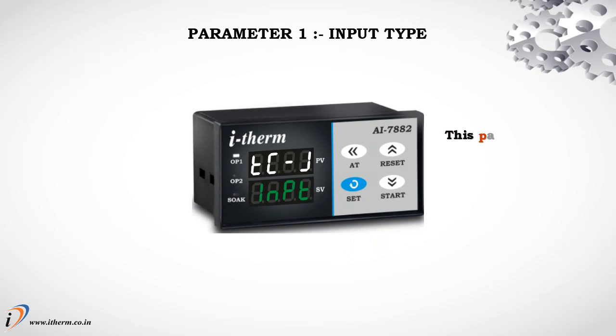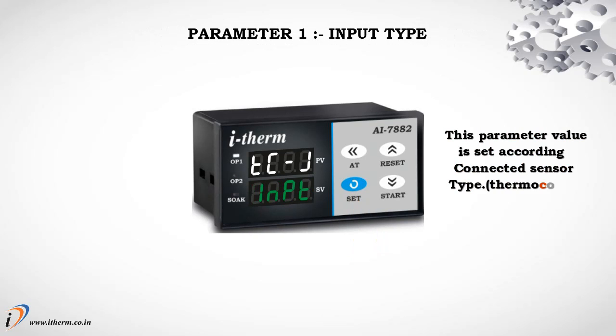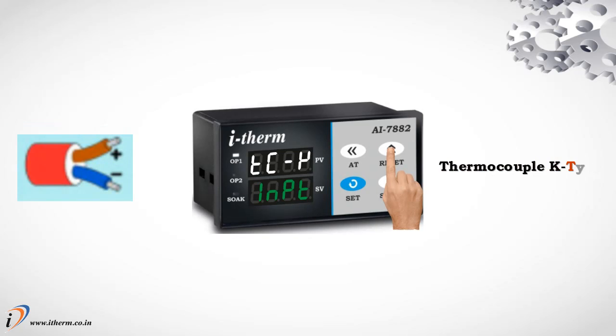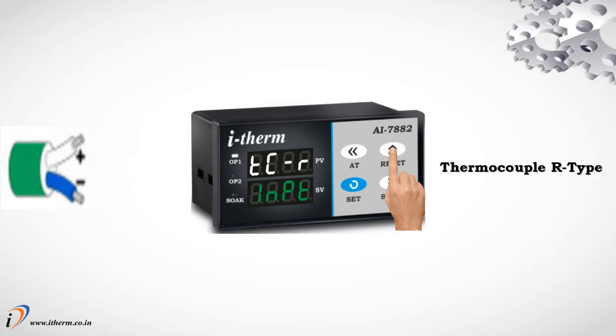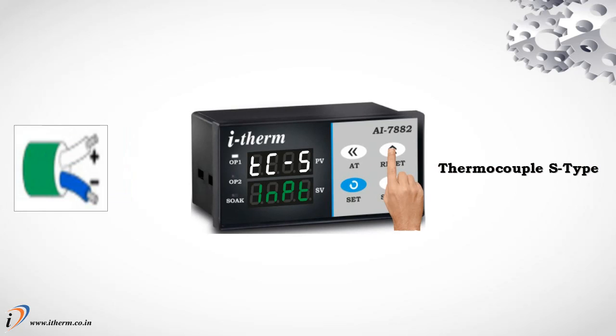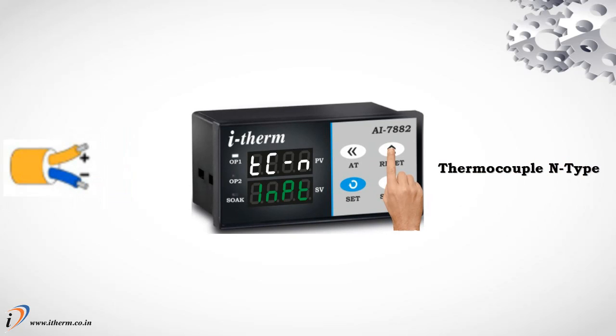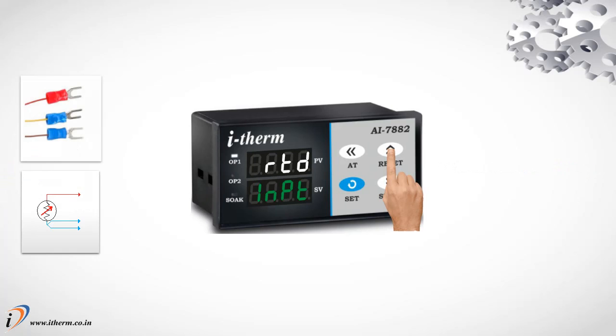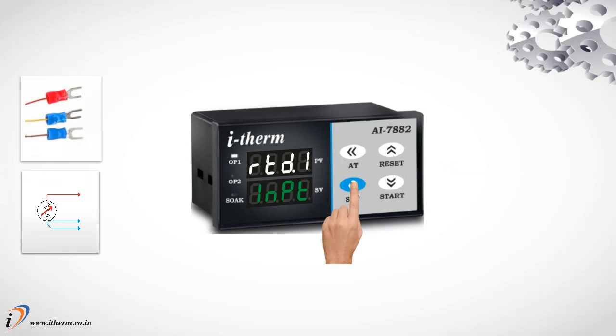Parameter 1, Input Type. This parameter value is set according to the connected sensor type. Thermocouple J type. Thermocouple K type. Thermocouple R type. Thermocouple S type. Thermocouple N type. Thermocouple T type. Thermocouple B type. PT100, 1 degree centigrade resolution. PT100, 0.1 degree centigrade resolution.